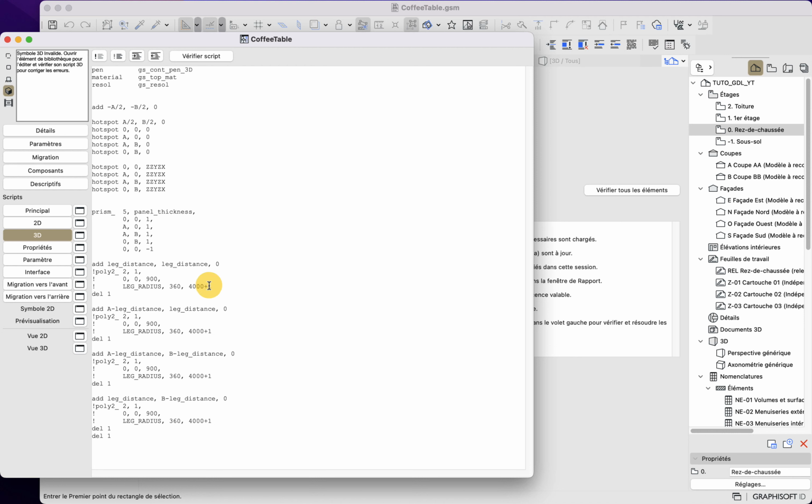So now we will do the same here. I can already tell you now, but we will have an issue with the representation when we finish the conversion, because there is something more that we need to add to the poly to prism conversion. So here, copy paste prism underscore, here, here, and here. And here we have the legs. The legs are of full height, so we will replace the code with prism as well. Here, here, here, and here.